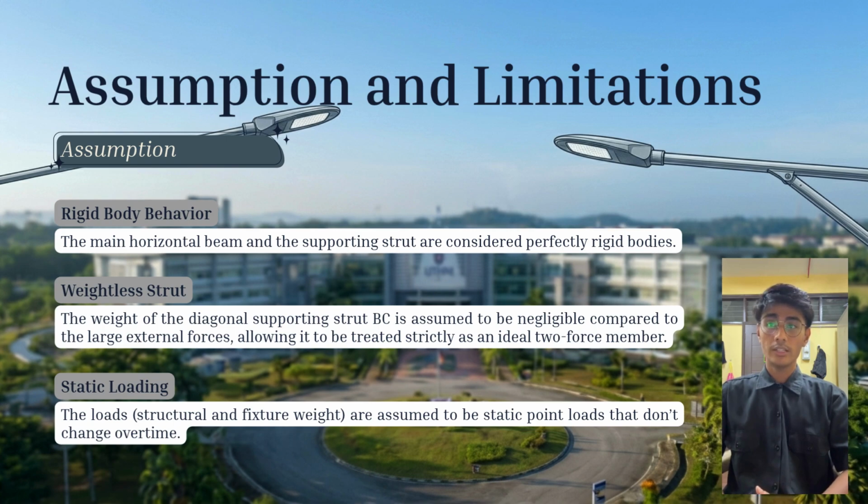The third one is static loading. The load structural and fixture weight are assumed to be static point loads that don't change over time, which means that it will stay 600 Newton and 800 Newton no matter how long it takes.